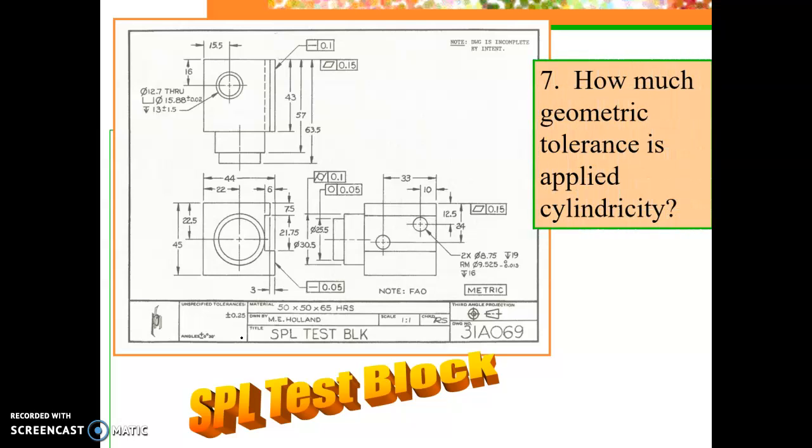How much geometric tolerance is applied to the cylindricity? So here is the cylindricity symbol. The tolerance on that is 0.1. How much geometric tolerance is applied to flatness? Here we see flatness with 0.15. Here we also see flatness, same tolerance, 0.15.